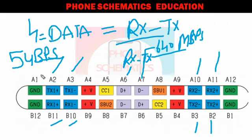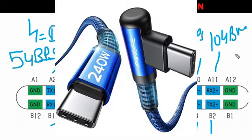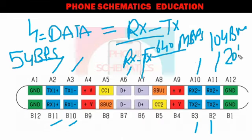Now in every 24 pin charging port, you will see these 8 pins, the TX1 and RX1 series and the TX2 and RX2 series, total 8 pins, right? Through these pins, your data speed goes up to 20 Gbps, when you connect C type to C type at both ends.